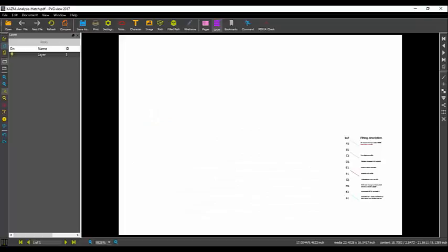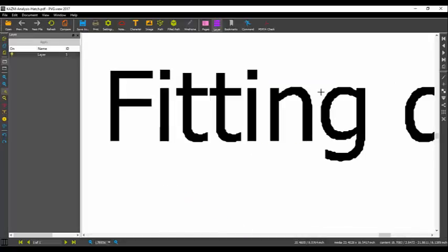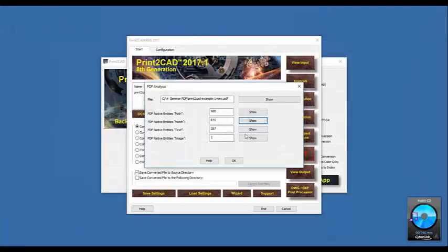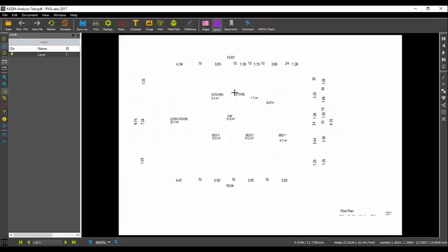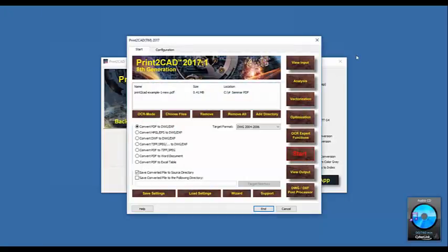And now you see here the hatch. And then, oh yes, this is a hatch, this is not a text. And I need here optical character recognition. And now this is a real text. Here you don't need to do something because this kind of text we can convert immediately into DWG text. So next step is, now you know the following. You have to take care of vectorization, but you need optical character recognition for a text, because the program will never make any optical character recognition for any conversion if you don't tell it you want it. Why?